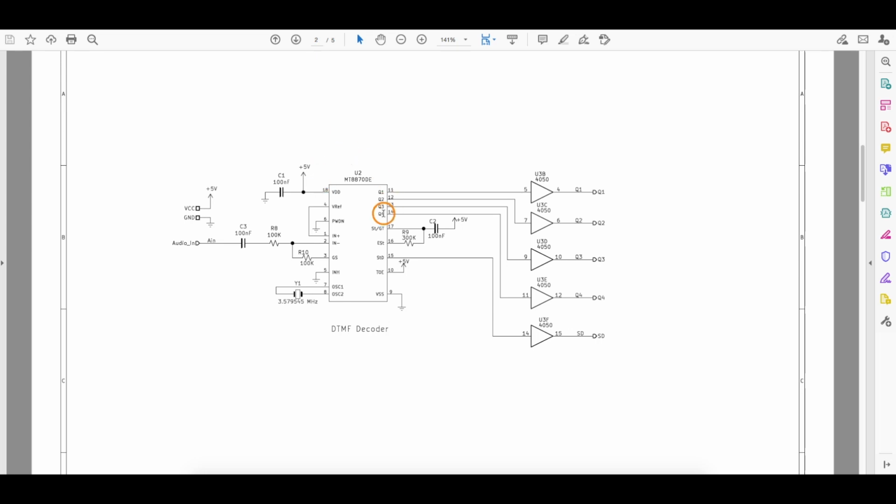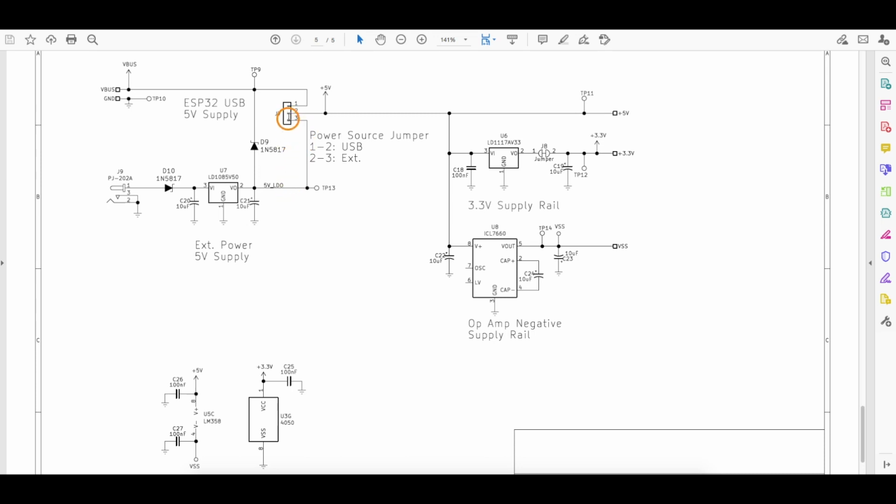So if we're powering this chip from the ESP-32 5 volt supply, and it's got a series diode drop, it's already possibly down to 4.7, which is violating the minimum power needed by this chip. It's probably fine, but I just wanted to make sure the specs are achieved. So that's why this jumper here, giving maybe a minimum of 4.9 volts, will guarantee everything on the board can run properly.